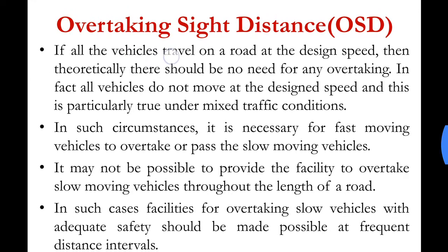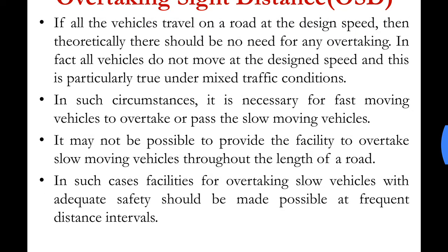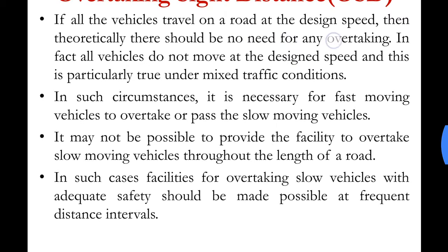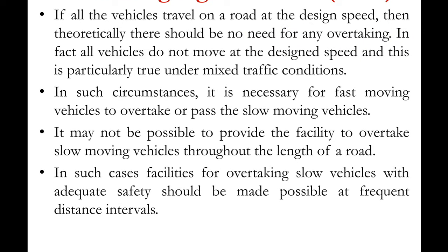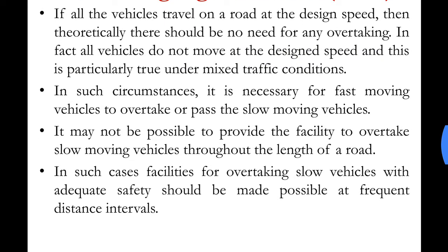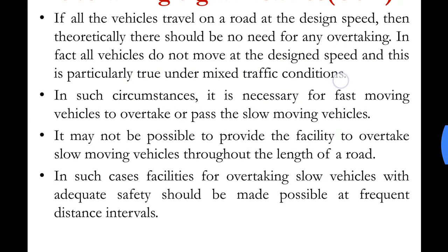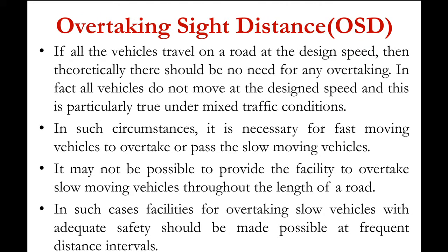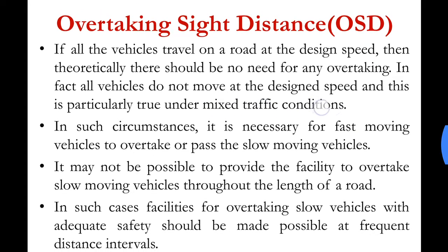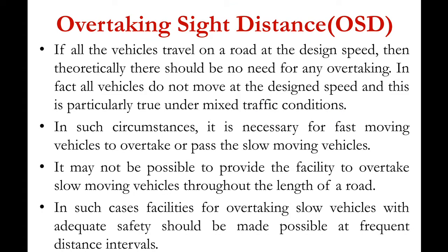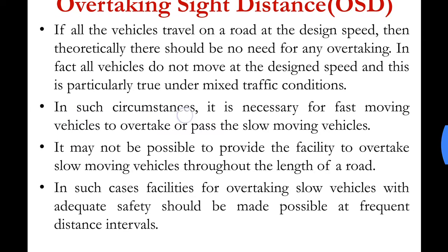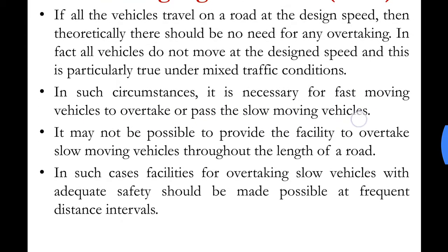If all the vehicles travel on a road at the design speed, then theoretically there should be no need for any overtaking. In fact, all vehicles do not move at the design speed, and this is particularly true under mixed traffic conditions. Okay, and here we need to note that in India we have mixed traffic conditions. There are different types of vehicles moving on our roads with different speeds. Hence there is a need to overtake. In such circumstances it is necessary for fast moving vehicles to overtake or pass the slow moving vehicles.